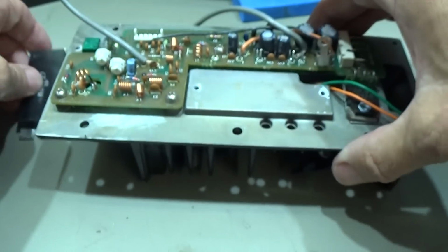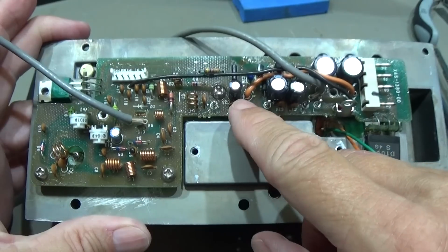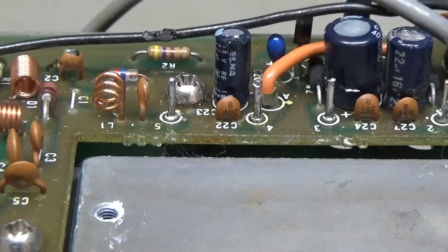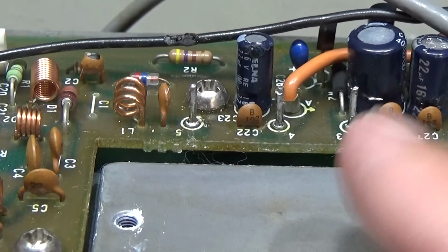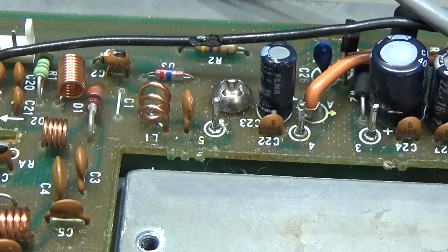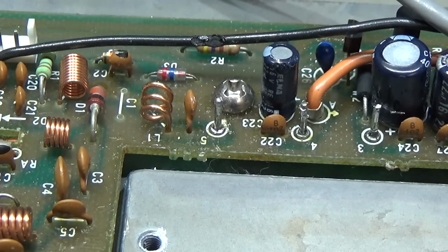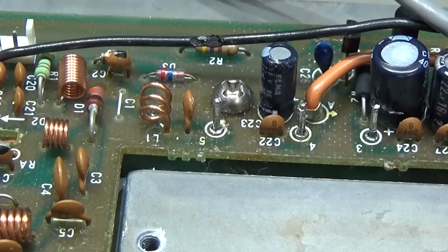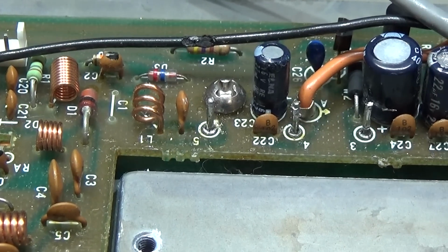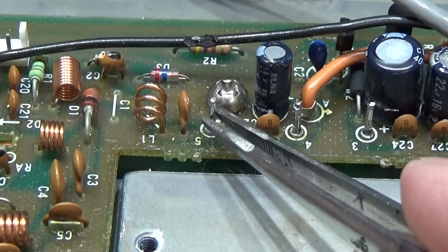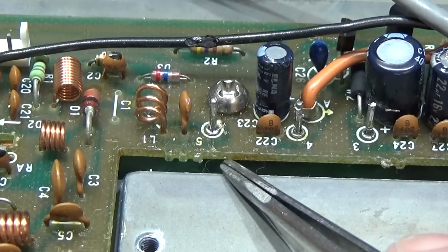We have to turn it around, these little soldering posts over there, and if we have the new one in and aligned in the right way, then afterwards we have to take the PCB out once again because we need to check the solder joints underneath.